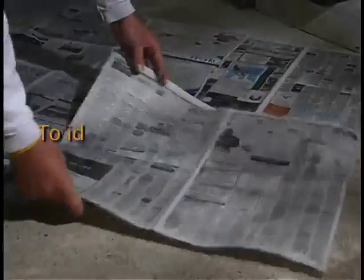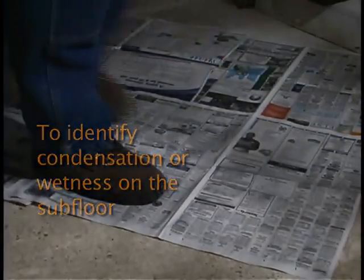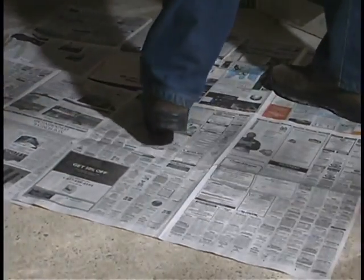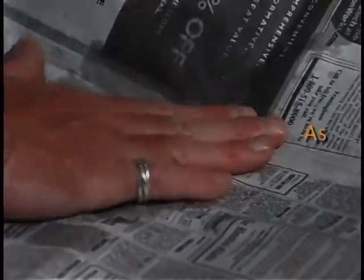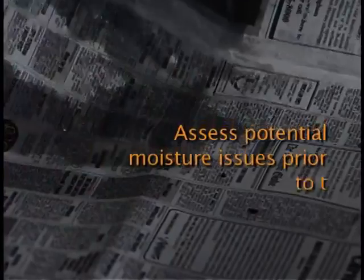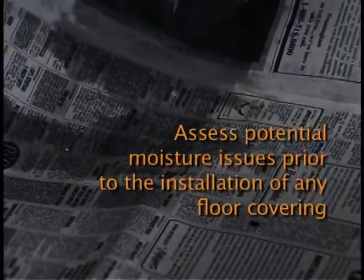Here is one very simple suggestion to help you identify condensation or wetness on the surface of the subfloor. Place a dry piece of newspaper over the area in question. Walk on the newspaper, then lift it up and inspect it. If the newspaper is moist or wet, then MVP4 should not be used, and you'll have to assess a potentially serious moisture concern with the homeowner or related contracting parties before the installation of any floor covering.